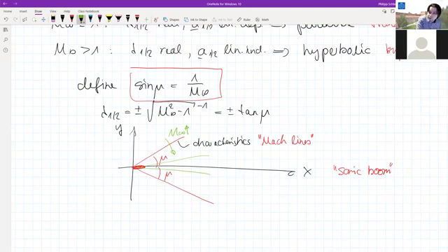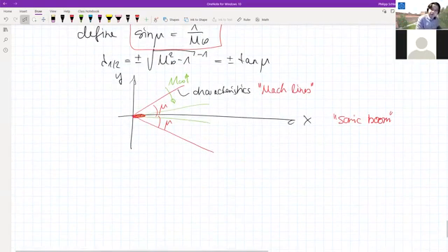But then what happens afterwards? When the Mach lines are vertical, can they get more vertical than vertical? Obviously they cannot, and the Mach lines also cannot go forward. So at that point, when you are vertical and you decrease the speed even more, it turns out that the Mach lines disappear, and the problem goes from hyperbolic into an elliptic problem. So physically, we can directly understand that something must happen at Mach being 1.